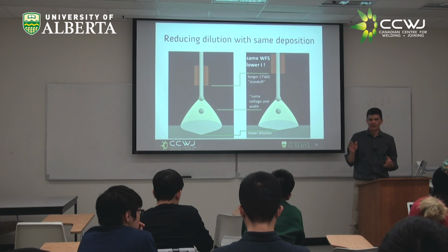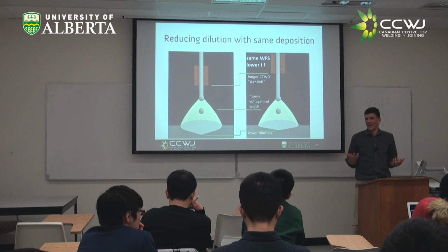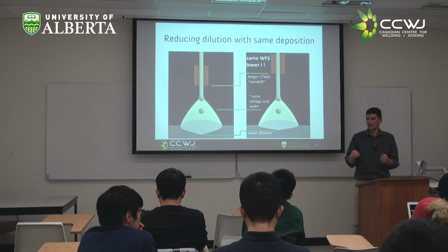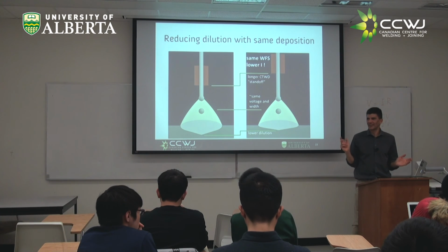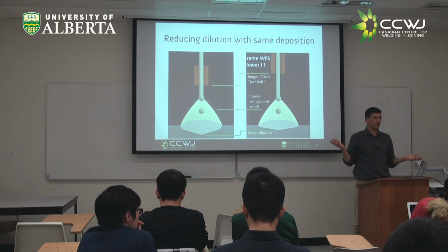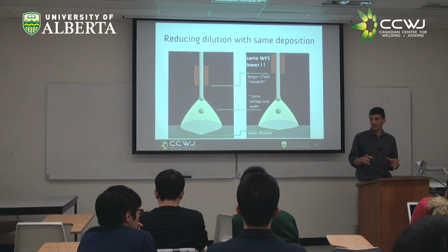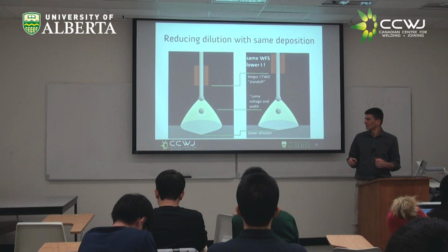Super, super interesting. Now, what's the catch? Well, you need to buy a new machine. And a machine that can do both polarities costs more or less like two machines, one for the positive and one for the negative. It's not quite like that. So what do you want to do? In this case, the guy needs to go with a wrench to change it. In the other case, you would move the AC balance the way you like it. Who are you? The guy who bought a fancy machine or the guy with a wrench? I don't know. But whoever you are, now you know what to do, and you can start making your decisions based on this.